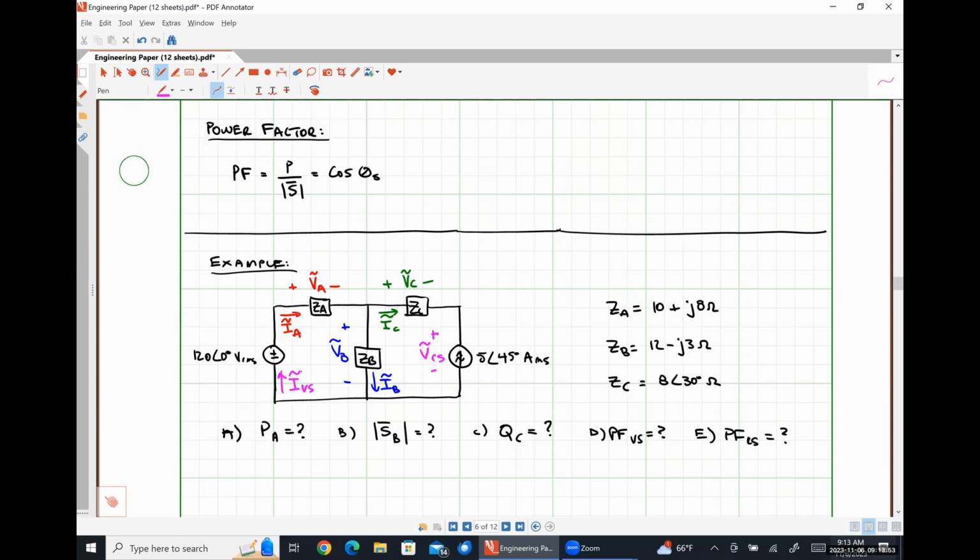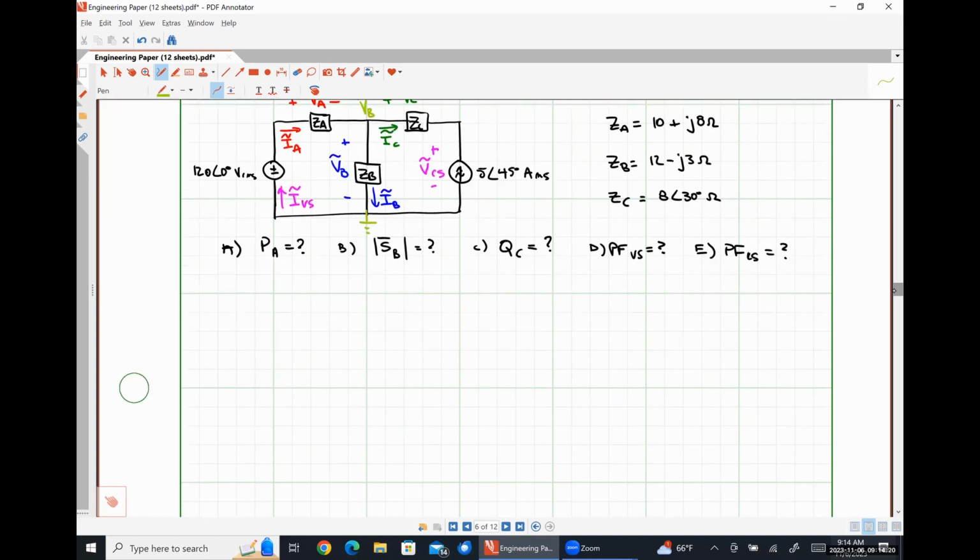Okay. So if I put my ground here, this nodal voltage is literally the exact same thing as the VB that we need to find anyway. And once I find that, just using algebra, I can figure out everything else pretty easily, right? There's a couple of other things that we could do, but this will be a pretty easy way to do stuff. All right, so applying Kirchhoff's current law at this top middle node,